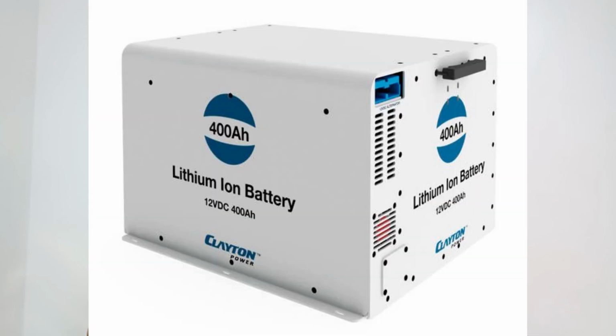We go into the second technology of batteries used in solar energy, which is the lithium batteries. Under lithium batteries, we have the NMC batteries. The NMC batteries have a high energy density compared to their size, and that's why they are used in electric automobiles like electric cars, electric bikes, and electric scooters. They are more prone to fire outbreak. They also have a shorter lifespan, and they have a charge cycle between 3,000 to 4,000 charge cycles.